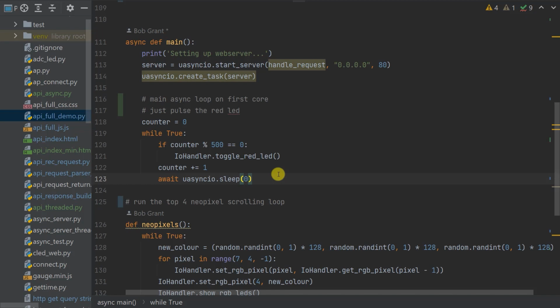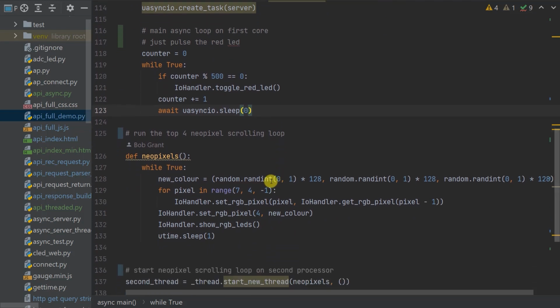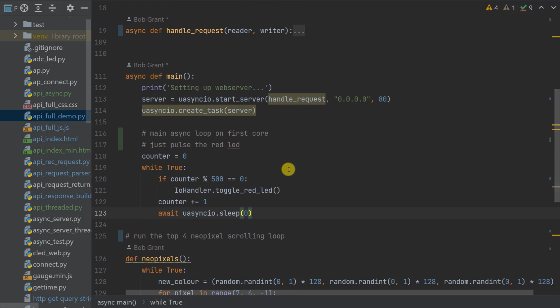So in breaking up your code, do have a think about whether it needs very fine timing, when it would handle best on its own core, or whether it can be a little bit flexible in its timing, when you can then use that extra time on our asynchronous side of things to just do a little bit of housekeeping and general control, which isn't as time critical, as I said. So that covers all of the code I want to do on the Raspberry Pi Pico or ESP32 side of things, on the MicroPython side of things.